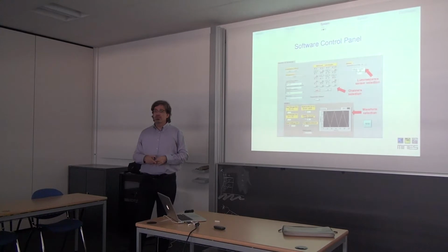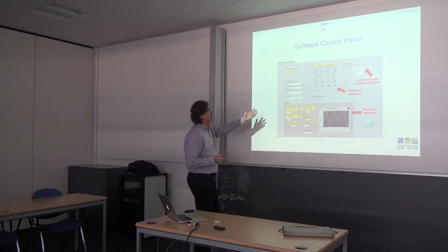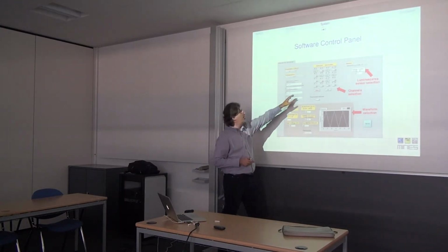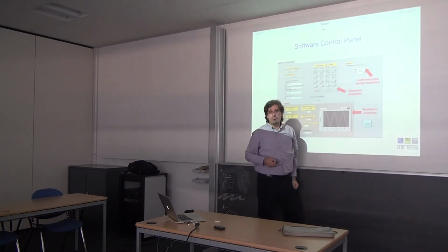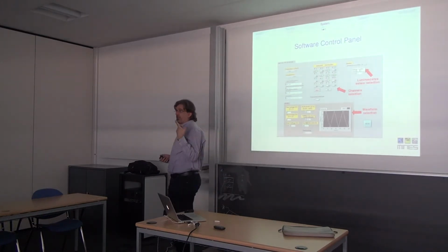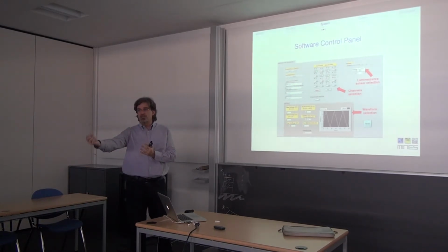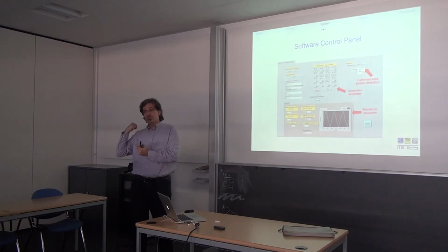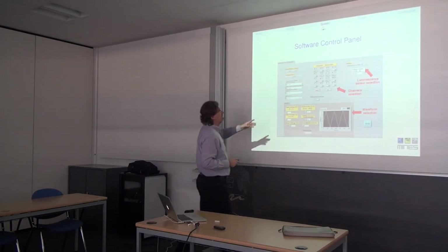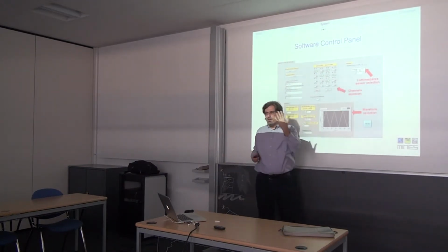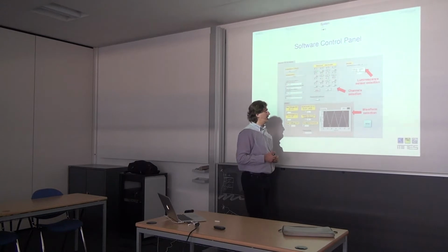Now, the software we are using now is based on Python. We changed it to the Python language, but of course the concept is the same. We have the possibility to choose which channel you want to use. We have also the possibility to choose the photodetector, because we characterize the photodetector, because we have a direct comparison between the voltage I have with the photomultiplier. I have a voltage of measurement, and the voltage is related to the quantity of light I have. So depending on the specific sensor I'm using, I know the quantity of light because we characterized it and we calibrated our system.